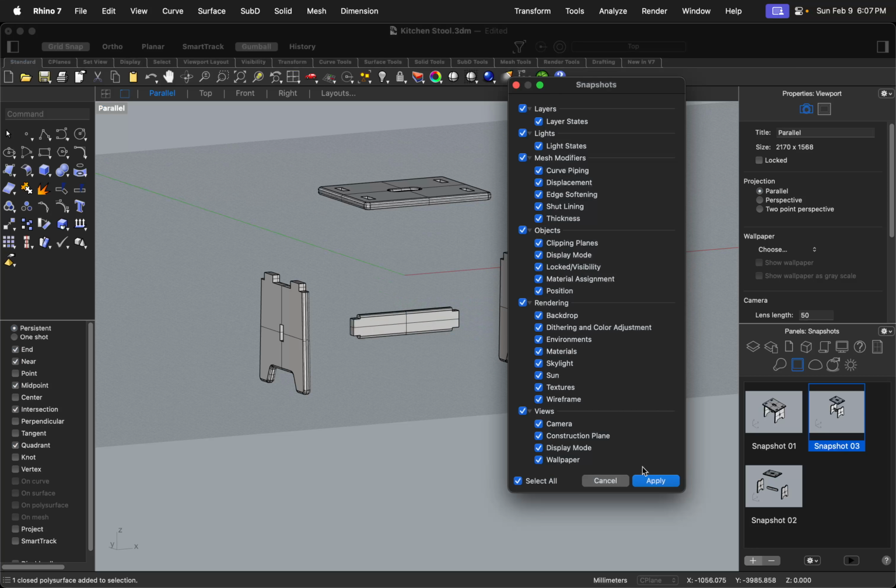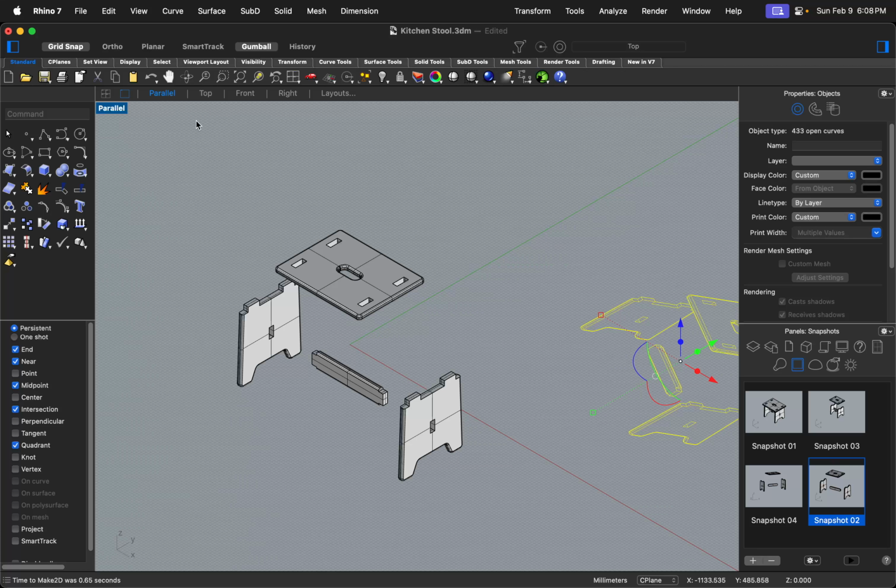And if you're happy, you can then select the extruded view drawing. Remember to set it back to the perfect southeast. And then go with make 2D drawing. This time around, we don't need to make everything, we just need one automatic drawing. So I'll just click on the wheel and then hit apply. That's quick.